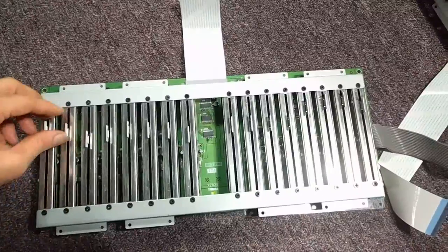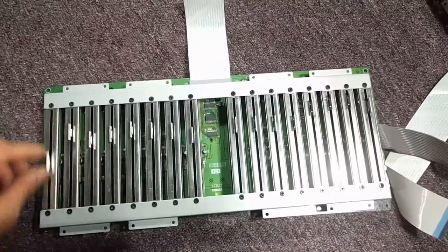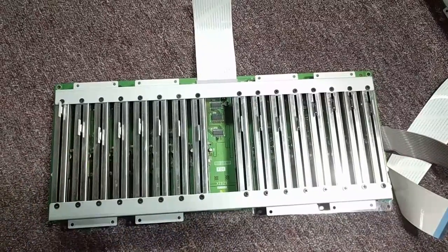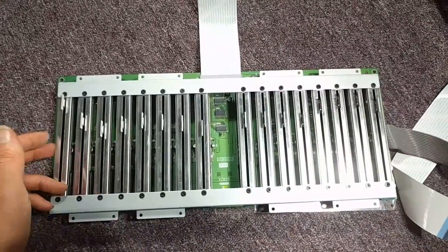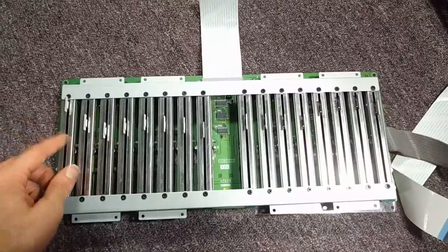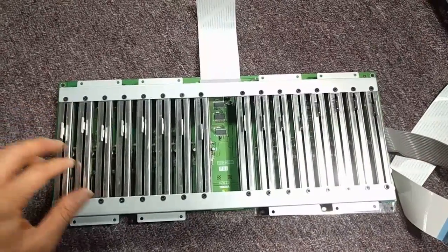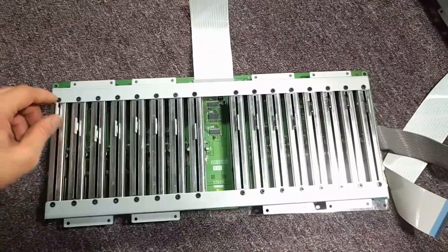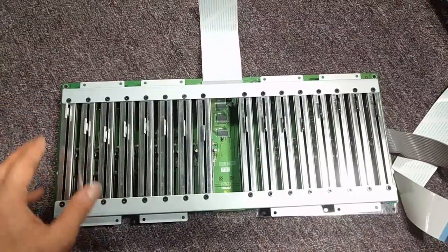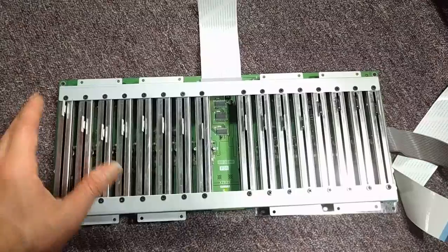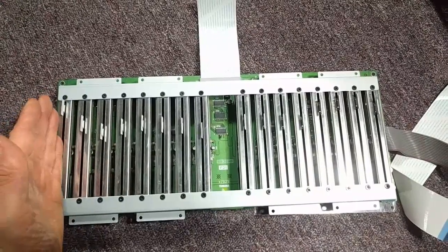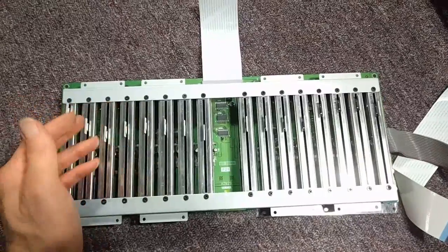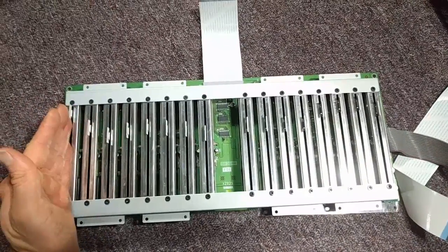This was channel 1. What had happened is, with these, they just get gunk in them, just dust and stuff over the years. And when it gets really bad, it gets really bad. In the case of this one, it actually broke off a bunch of the teeth that slide on the resistive element. And then it did something that I haven't fully figured out, but it made the track just ever so slightly off on the y-axis here.